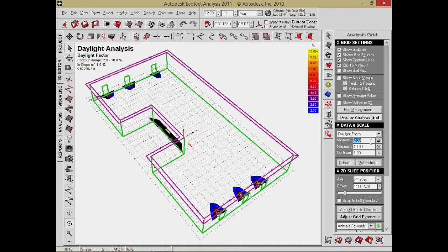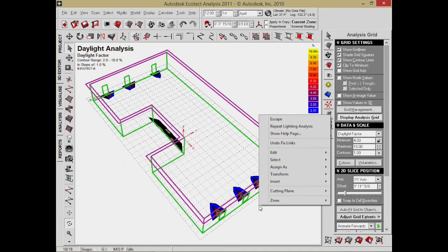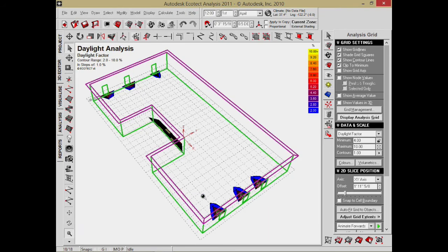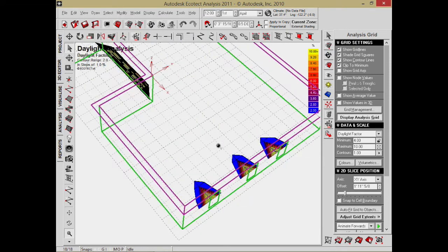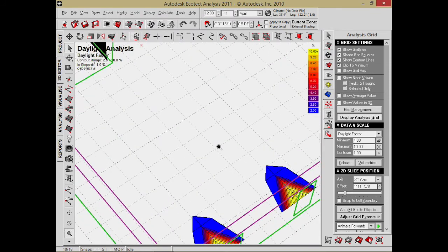So contours, let me zoom in and show you what the contours are. I'm going to pan that up. The contours are supposed to be, as best I can, of my value going 4 to 10, I'm basically saying put a contour at every one. It seems to have a lot more contours in there now, so I'm wondering how it works in terms of the overall scaling. But as that number gets bigger, you'll have fewer contours.